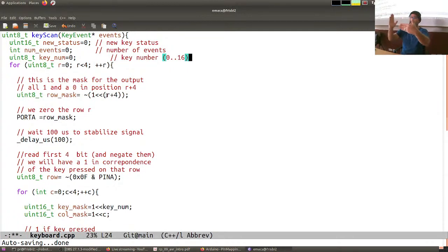In this way, I'm going to cover the 4 most significant bits. Okay? Is that clear? Then once I have a mask consisting of a 1 and all zeros, or 0, 1 and all zeros, and so on, I can negate it and get the enabling that I want to have on the rows of the matrix. And this is the big game.